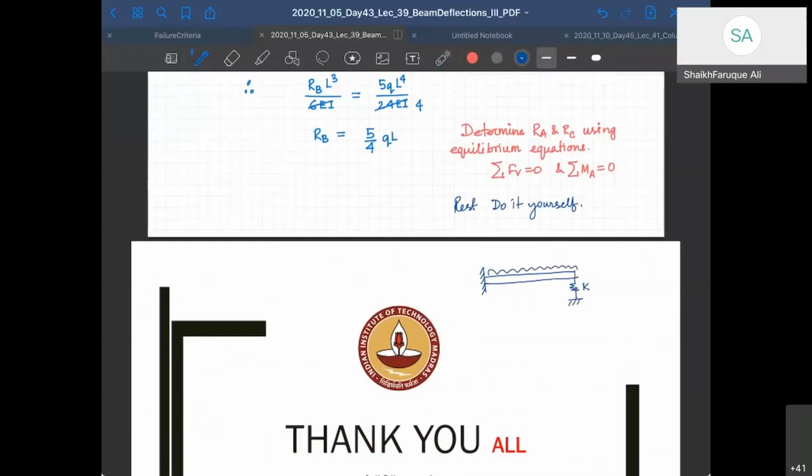So instead of a support, I have a spring here. This is called a support settlement problem. For example, this comes from a real structure. Let's say you have a beam-like structure and you had a support here. You know that the soil here is not in good condition, so it can fall in. So it can go like this, and this is your deformation. This is called support settlement.